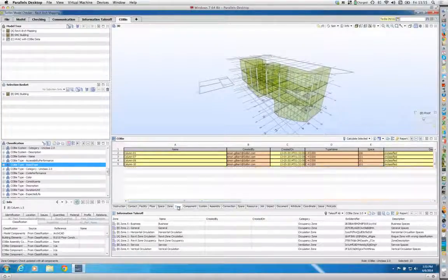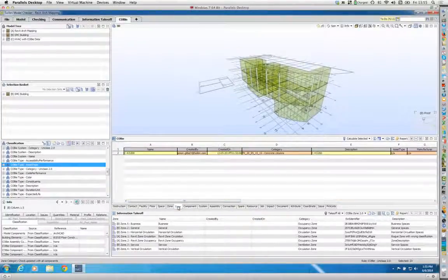Now, we did quite a convoluted way of fixing some of the issues to do with the type sheet, and there are a couple of functions in the Revit exporter now which fix all those issues when they come out. So it's very rare we have to fix any of the types. The only things we probably have to look at, which I haven't checked yet, is anything that is a wall sweep and whether or not they include the ID on it. But I think they will from the new functionality that's there.